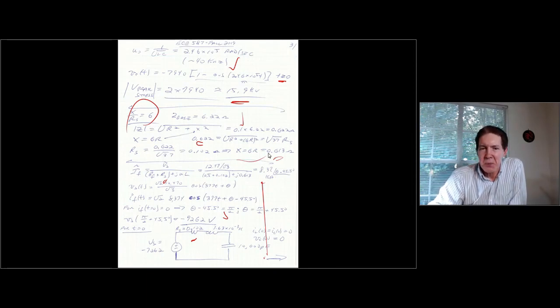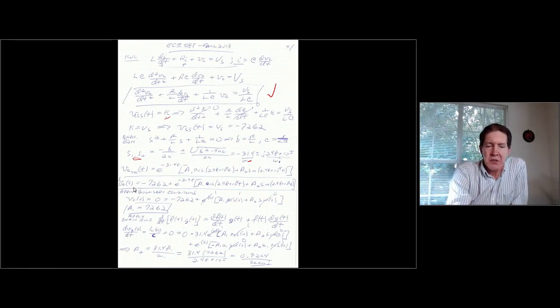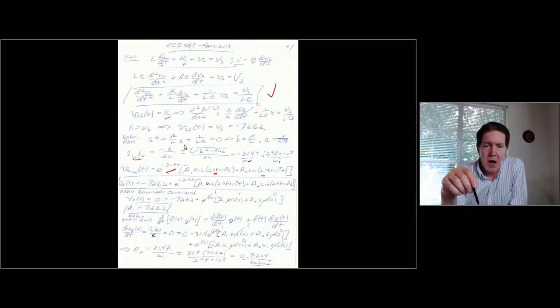It does change it a little bit, but it's only changing it by about 1% or so. So it doesn't really factor into changing that resonant frequency too much, but it causes a slight change. So now if we look at the transient portion of this, instead of just having A1 times a cosine term and A2 times a sine term, we have to put this exponential damping term in here, which means that as time increases, we're going to have kind of an envelope that's going to decay out with time.